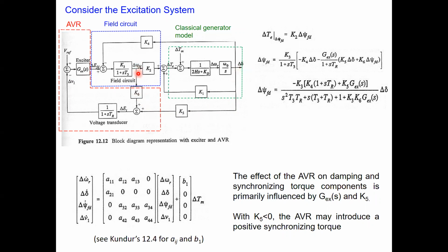So as a whole, in the SMIB system, remember, there are 6 constants, K1 and then K2. In fact, K3 we get from here. I have not shown it, but we transform this 1 plus sT3 into another constant, a complete transformation. We get it here, basically it is K3. Because in some books, you will find that this term has been included with the K3, that is also possible. And next, this one is your K4, here is your K5, and this one is your K6.